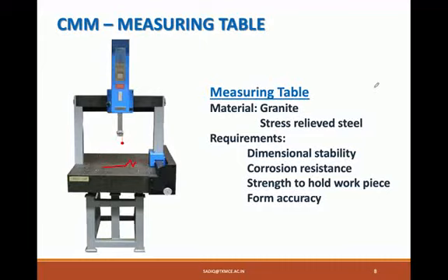perform the measurement. Granite is a naturally seasoned material, but granite has got a problem that, being a natural material, it is porous. So when we use the CMM having granite slabs, it is to be specially taken care that oil should not be spilled on that, because oil can go into that and finally it can develop cracks over a period of time.